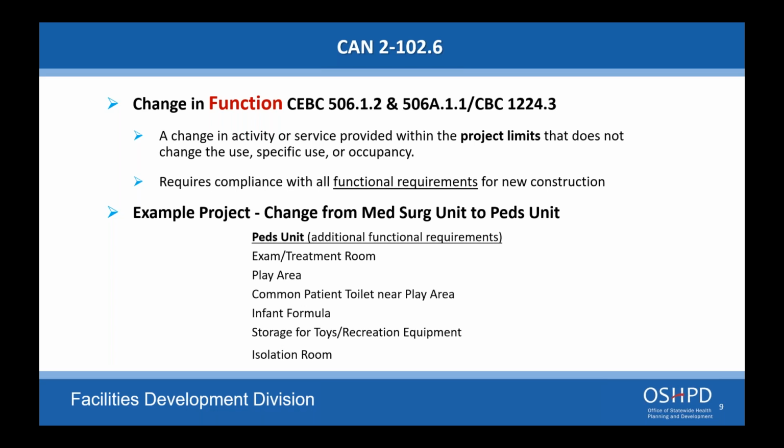Again, what we tell owners all the time, the rest of the area is demoed. Again, it depends what's non-compliant. If it's just bracing, go ahead and add it. If you're MPC compliant, go ahead and add the bracing while the room's open and you have easy access. It's better than coming back in later into an occupied space and doing it. But as a general rule, you should not be required to upgrade those systems if they're not otherwise being touched in that space.